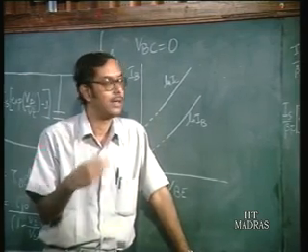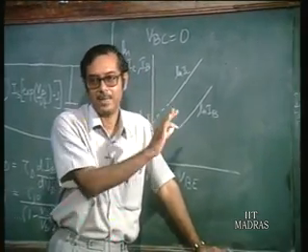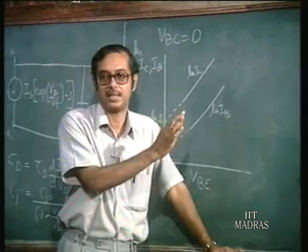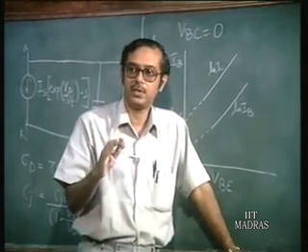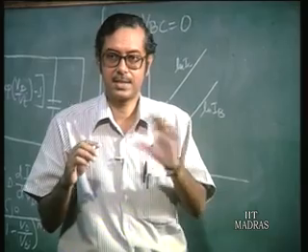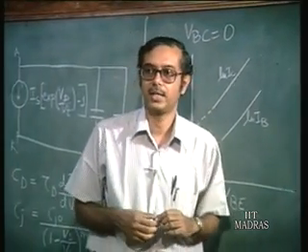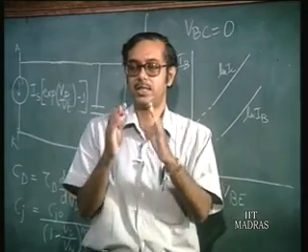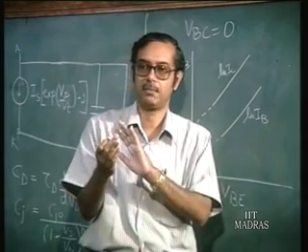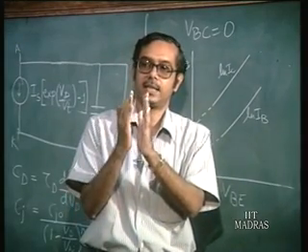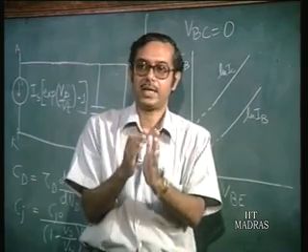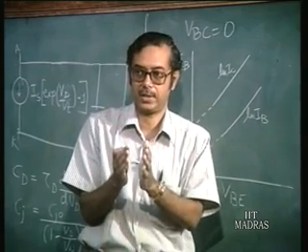So this is the basic model, which is used to understand many effects. But if you really want to do exact analysis, some other corrections taking into account other effects, like the early effect, have to be done. Because what she's referring to is that if you reverse bias the base collector junction, the base collector depletion width is going to change, which changes the effective base width.